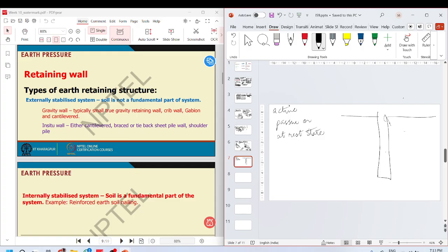I want to calculate the lateral pressure here, and I know that this is completely in equilibrium. There is no active or passive, there is no movement of this structure with respect to the soil, or the soil with respect to the structure, such that this is at total complete rest. This is called the K naught condition. Just at rest, soil is not failing in any way.